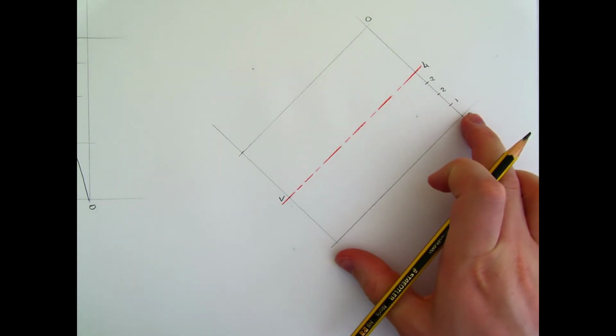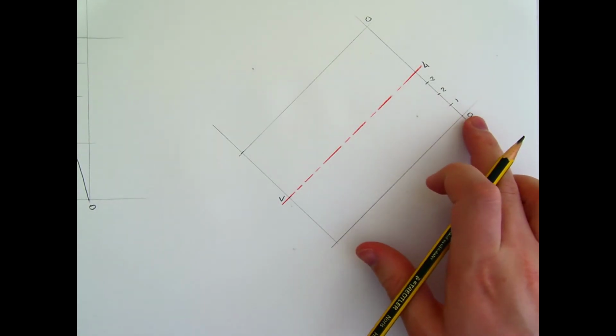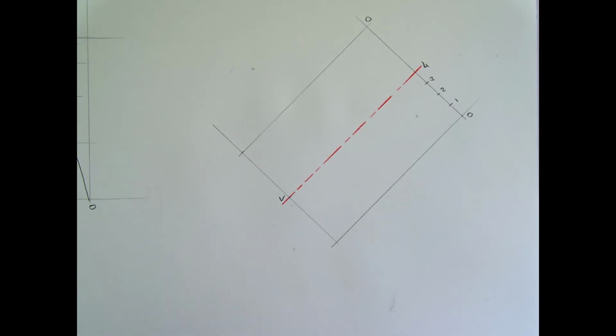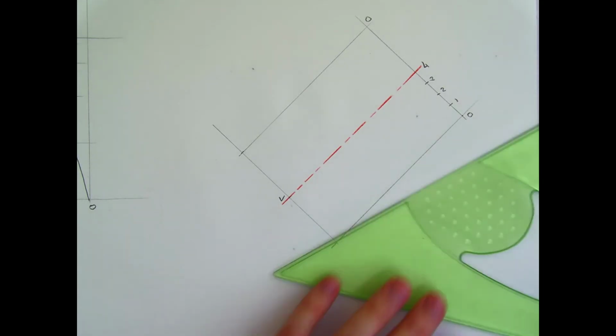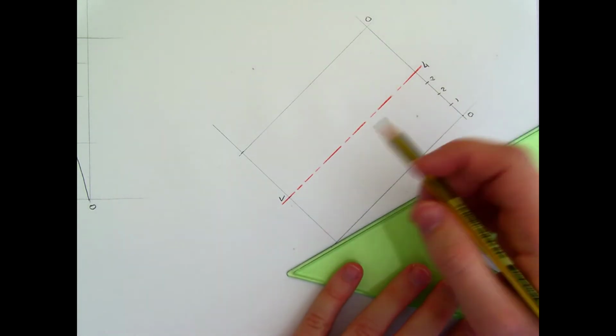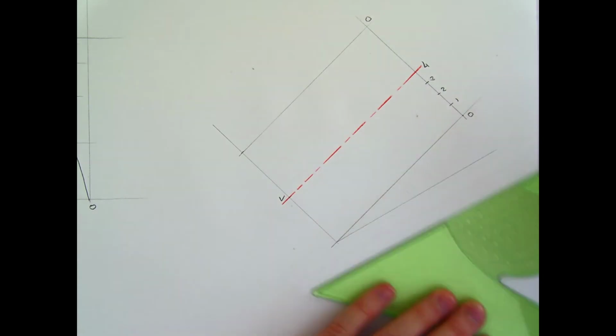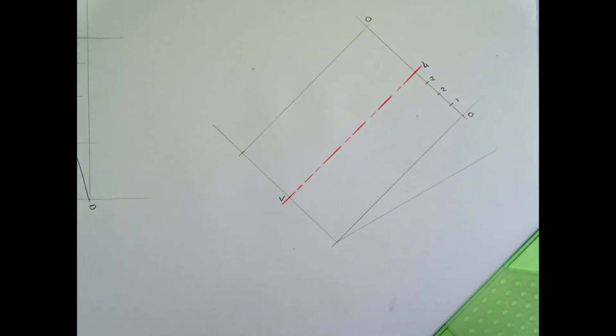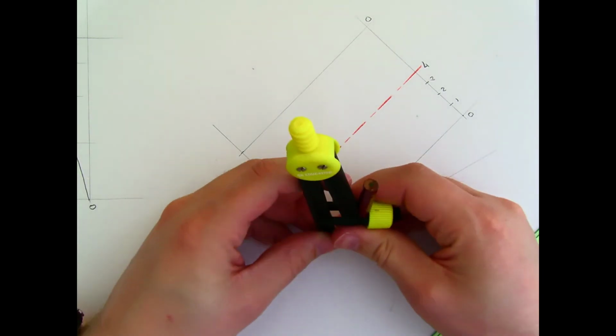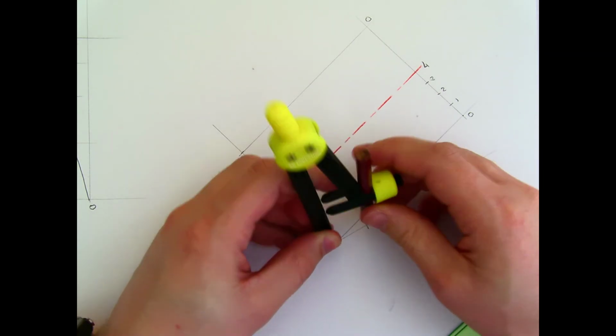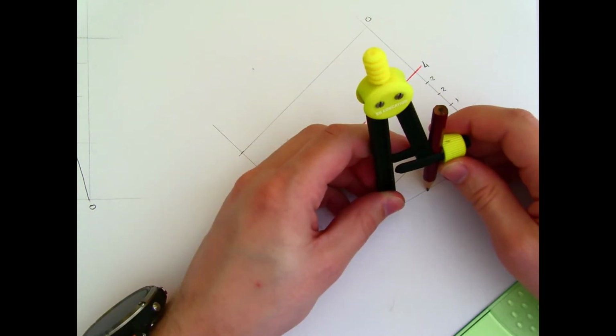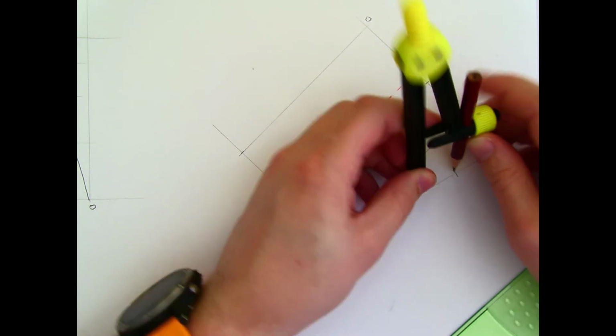Can divide the side here up into 4 equal parts as well. So 110 does not divide evenly by 4. So I need to draw a line off at an angle. If you used 5 in this case, it would have worked, but just to show how you draw it. So line off at any angle, mark off 4 sections of equal length, 1, 2, 3, and 4.